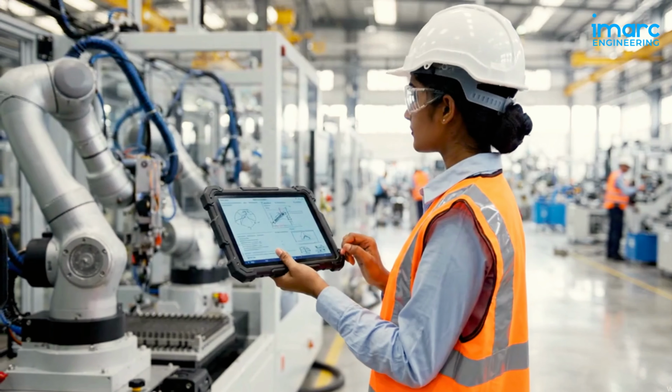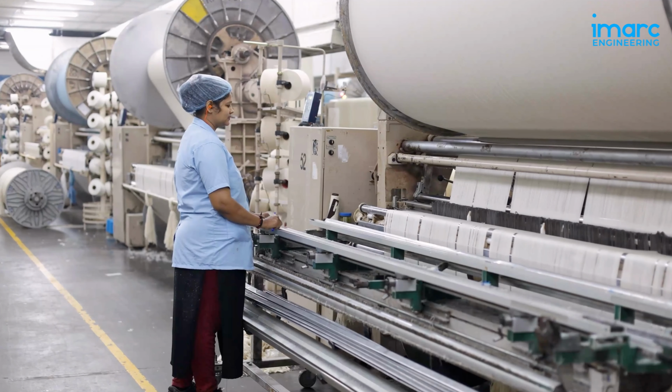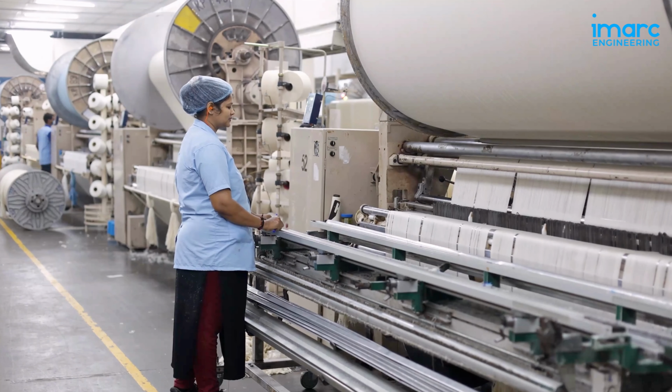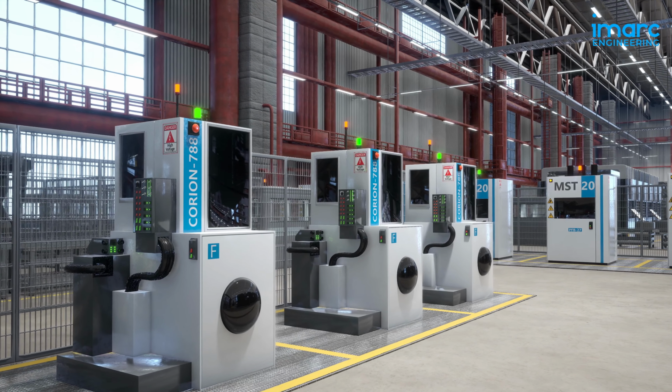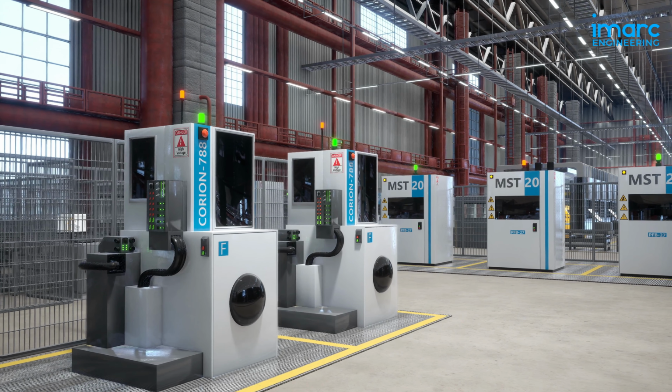One of the most common mistakes is using too few observations. Fewer than 20 observation cycles can make the standard time unreliable. A properly conducted time and motion study can significantly reduce costs and improve productivity. However, these benefits are often lost when two critical steps in the process are overlooked.